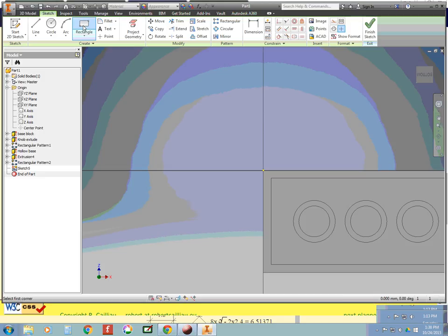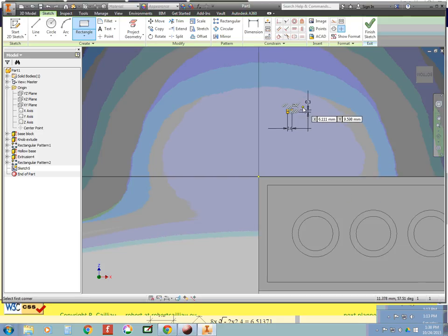And we're going to use the Rectangle tool. And up here, I'm going to make it 0.6 wide. Tab to go to the other dimension by 0.3 tall. And again, it has all those constraints turned on. I don't want to see those, so F9 will turn them off. And then oh, we're already out of the rectangle tool. That's good. Now we need a dimension, or we need to locate this. So I'm going to bring it down here onto our drawing.